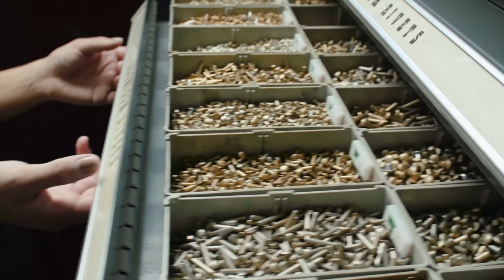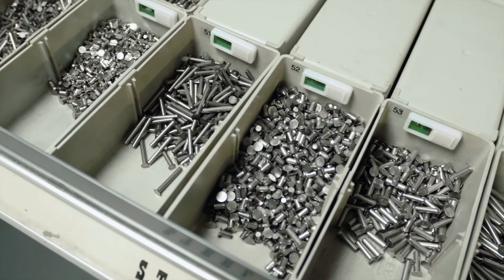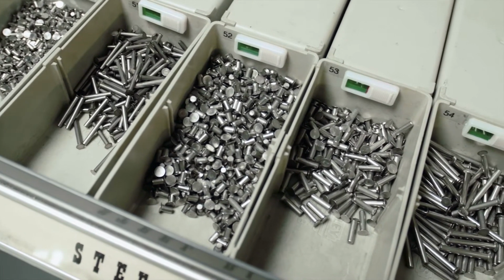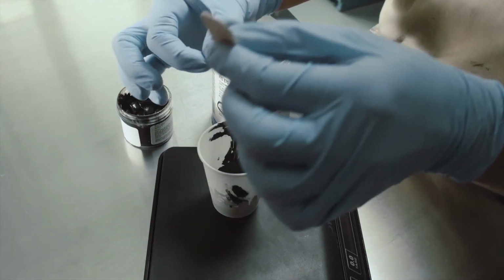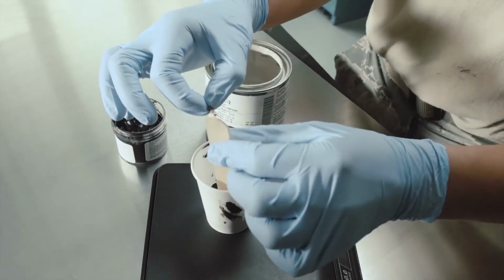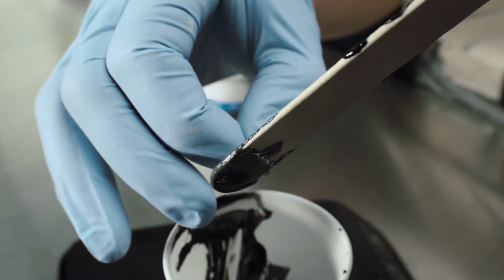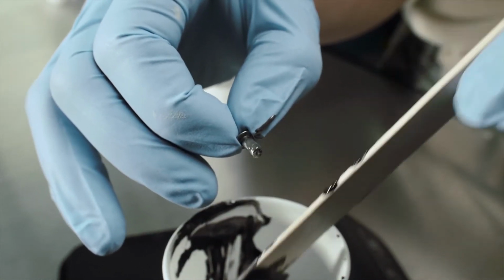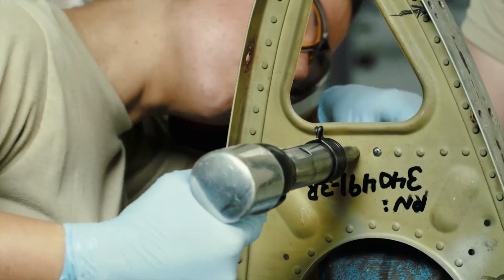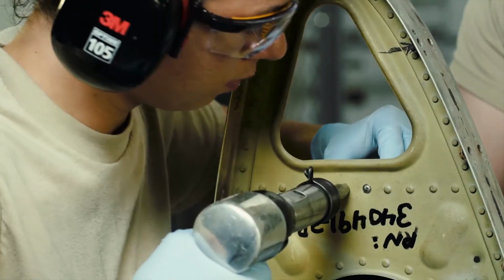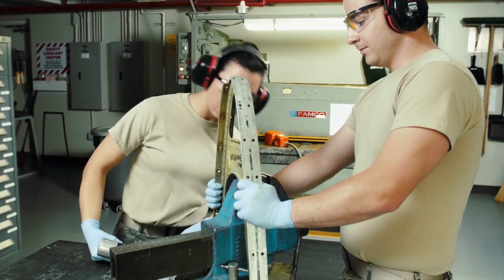So the engineer might specify an aluminum fastener if it will provide the required strength. If an aluminum fastener isn't strong enough, the engineer might require that a steel fastener be installed using primer or a sealant to avoid direct contact between the fastener and the aluminum skin. The sealant or primer electrically isolates the anode from the cathode and also helps keep moisture from becoming a corrosion cell electrolyte. Eliminating any structural connection between anode and cathode and blocking the formation of an electrolyte removes two of the four elements that constitute a corrosion cell.